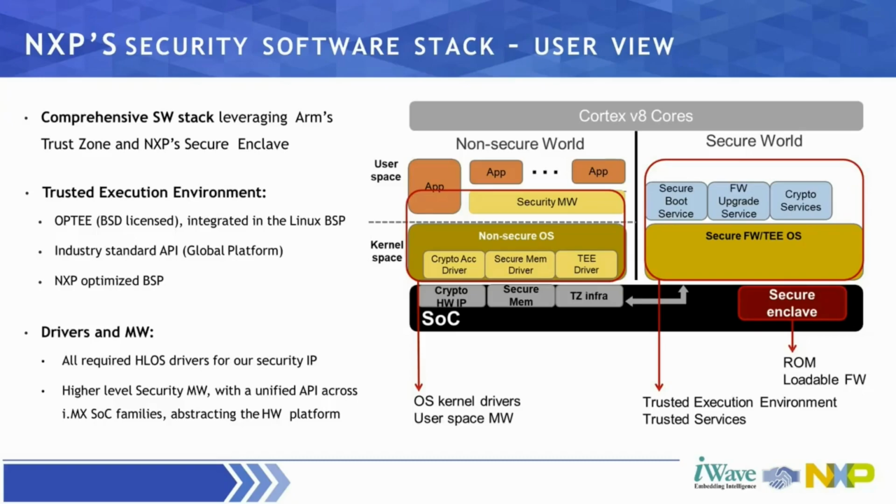We do support also some middleware, for example disk encryption with dm-crypt. We have added support for the CAAM driver with black key encryption, and that is tied to dm-crypt. We are also working on exposing cryptographic operations through OpenSSL or PKCS11 type of interfaces.